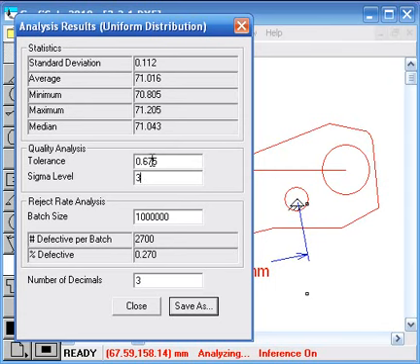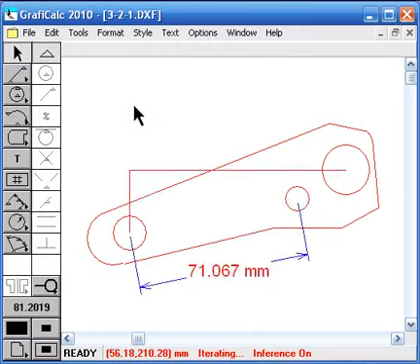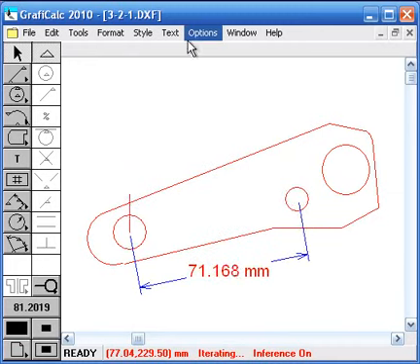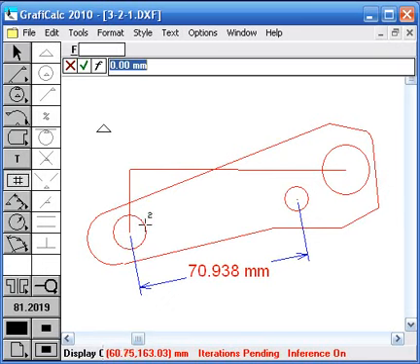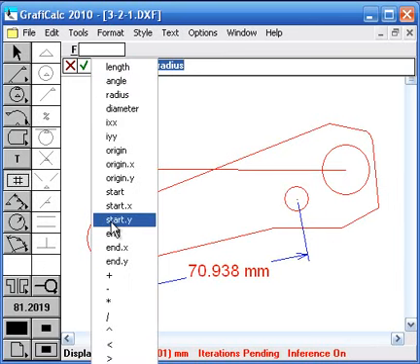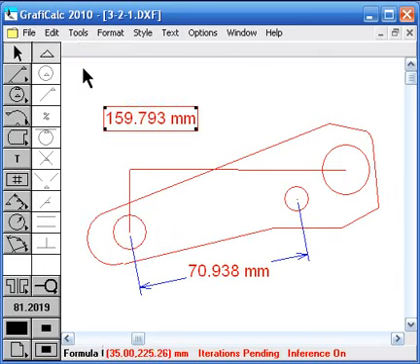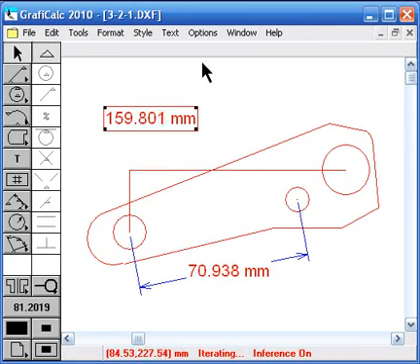So with a little bit of practice, this will become like second nature. As soon as you put two parts together, you can very quickly check the tolerances. You can also attach the calipers or the calculation to measure any part, any point of interest. For example, I want to know where the y coordinate of this is going to fall. So as the tolerance is going on, it's telling me the y coordinate. I can analyze and allocate tolerance.